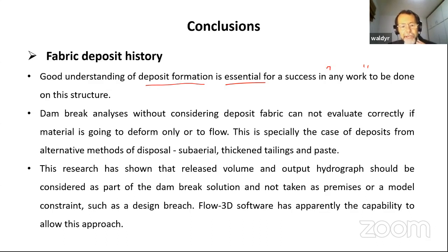As far as the dambreak analysis, without considering the deposit fabric, you cannot evaluate correctly if material is going to deform or is going to flow. You have to see, maybe the material is not going to move, or it's going to deform, but not to flow.